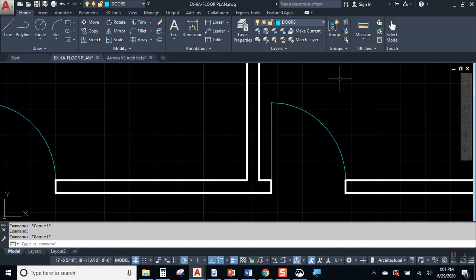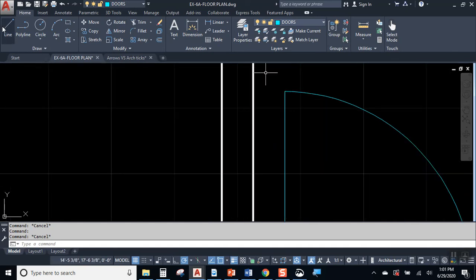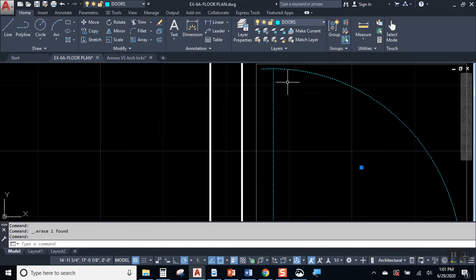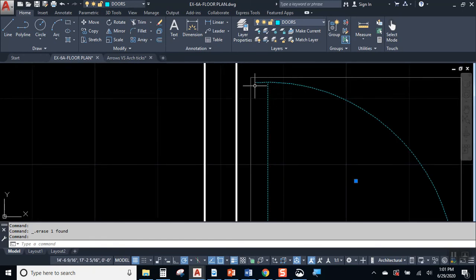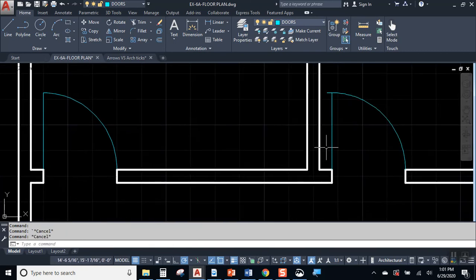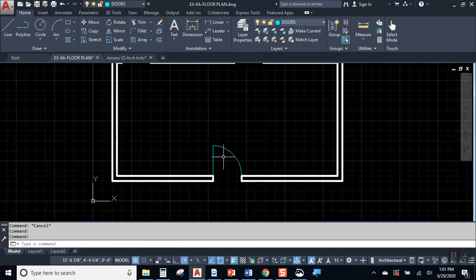So why would you want to turn off grouping? Well, I don't know, maybe what you want to do is you want to make a modification to your group. So you have to revert it back into geometry, and now you make your change, and then you turn grouping back on, and when you click it, well, now it's still a group, right? And what did I do? I just added a little bit of extension beyond the 90 degrees there for the arc. So notice though how changing this group did not change this group or this group.